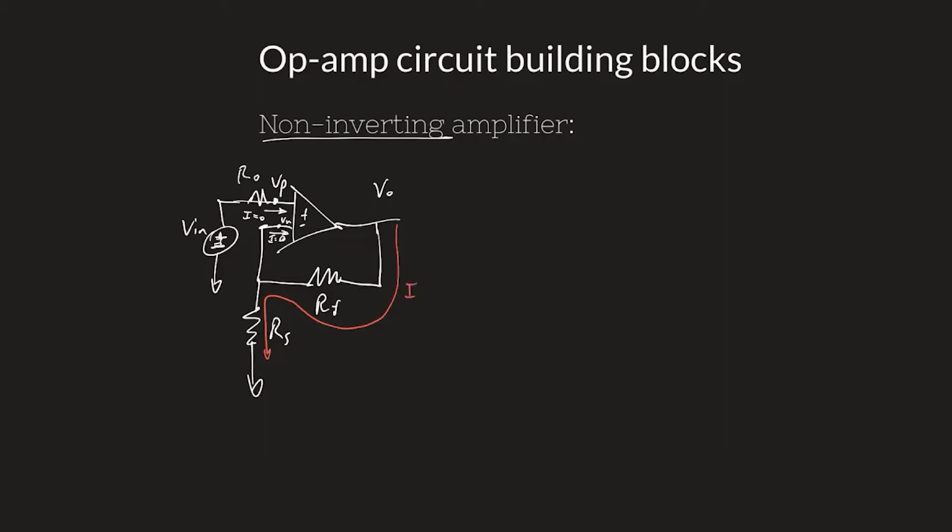So if I have current here, how do I solve this circuit? Well, I have Vout. Let's draw this as a regular circuit looking thing. Vout is acting as an ideal source, just supplying power coming out of its output here. It's not connected to anything yet. It just has this negative feedback, and I'll discuss in a minute why this is so critical. This is the feedback from the output to Vn, the inverting input. So this op amp is acting as an ideal source right here at the output.